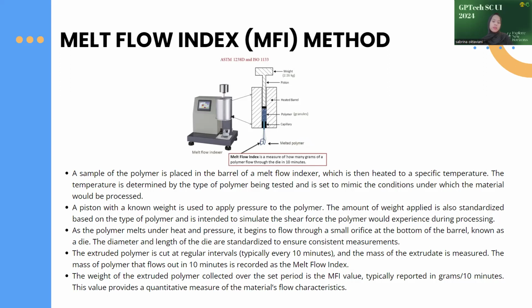And the last is the weight of extruded polymer collected over the set period is the MFI value, typically reported in grams per 10 minutes. This value provides a quantitative measure of the material's flow characteristics.